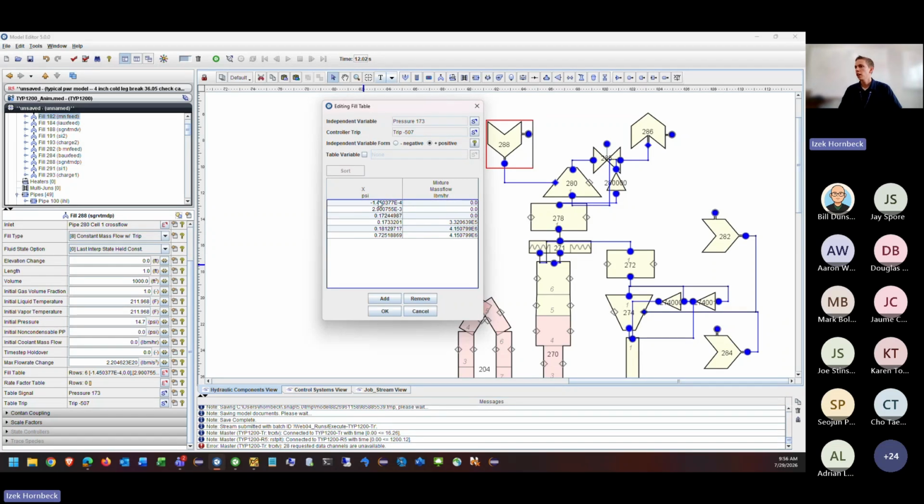But if you look, this is saying a pressure in units of PSI of this one, even right here, of 2.9 e to the minus 3. Like, that's just an unphysical value because our atmospheric pressure is around 14 PSI. And so clearly, something's wrong with these values here.